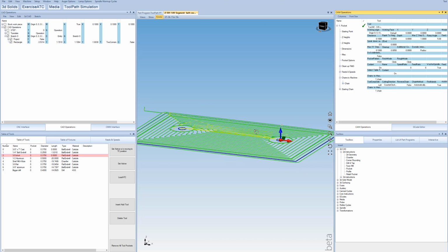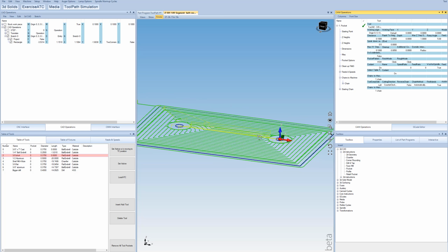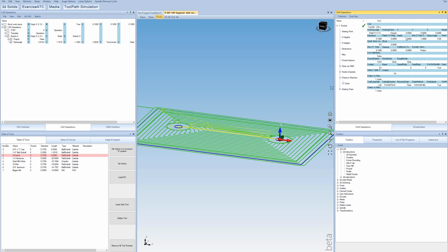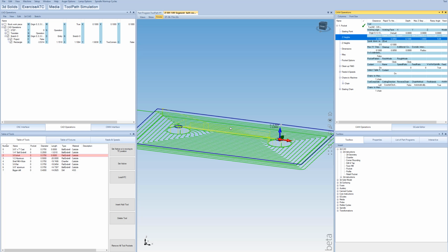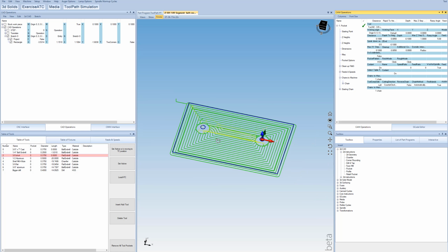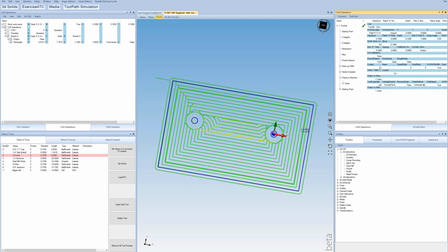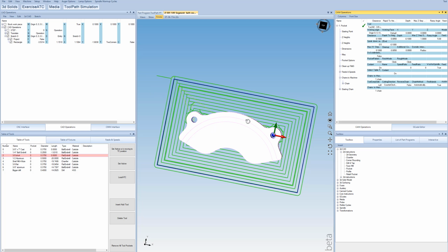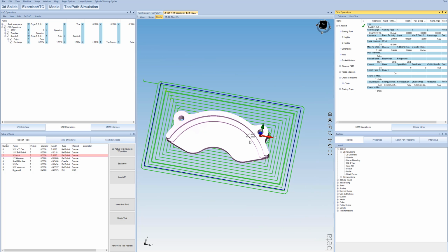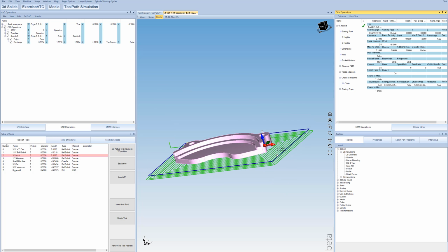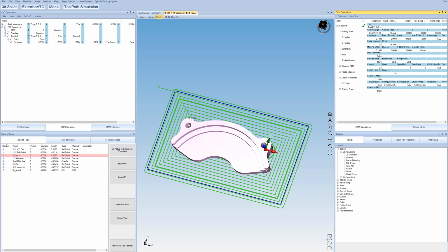Now, since we're working in 2D, we have to be a little bit conscious of the depths. So we'll do something like a depth of, say, 100 thou. When we cut this, it's going to basically take the entire aluminum block that we start with for our fixture and just recess the entire thing down except for these two circles. Then we can take our part and just place it right on top of those, and it'll locate very accurately, assuming that we make the fixture accurately, we don't have any tool deflection or anything like that, and the holes in our part are made accurately. Okay?